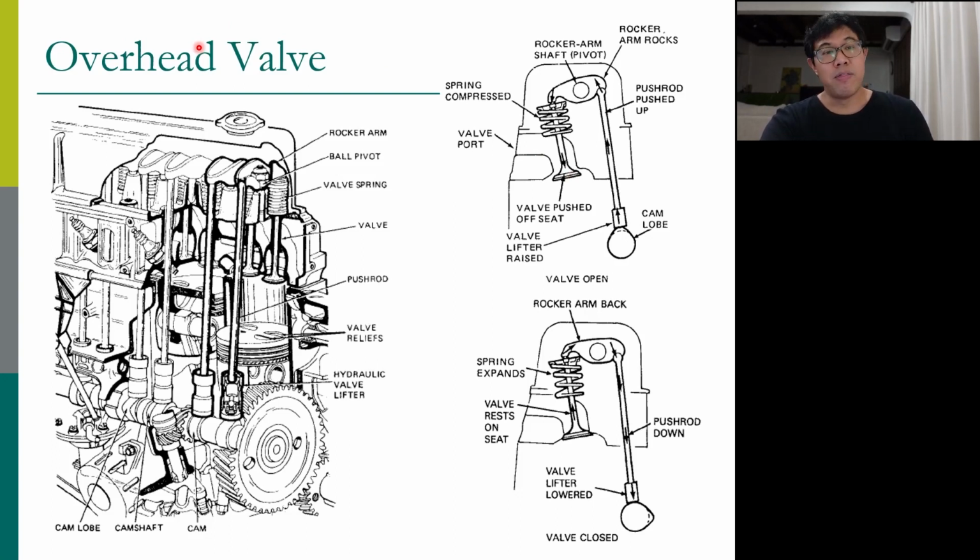Now, the drawback of this type is that it has many components, and these components are not really rigid. They can flex, they are a little bit flexible. It's not theoretically rigid. Which means that when you push the push rod up, instead of the push rod pushing the rocker arm directly, it flexes a little bit, and after it flexes, it pushes the rocker arm.